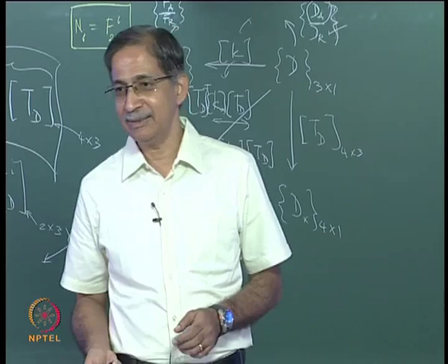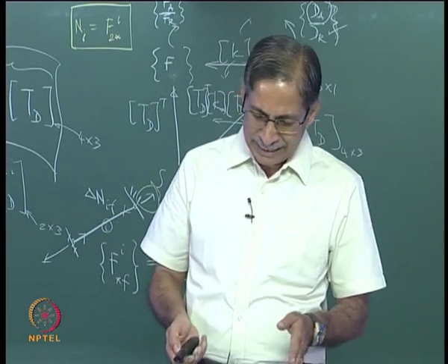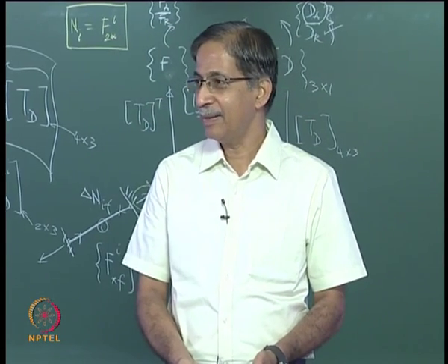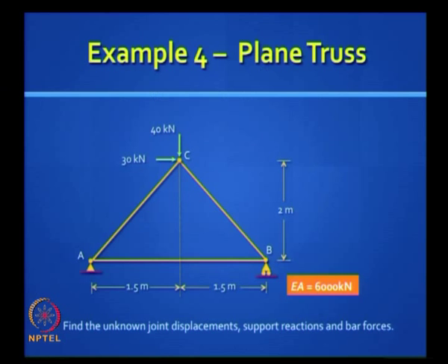We will take trusses, okay. We will take a simple truss to begin with. If you had to do this problem, which method would you normally do? No, first what is the question? To find the bar forces, what method would you use? You will use a force method. Why? Because it is statically determinate, you know the answers, and you can also use the principle of virtual work, the unit load method, to get the displacement.